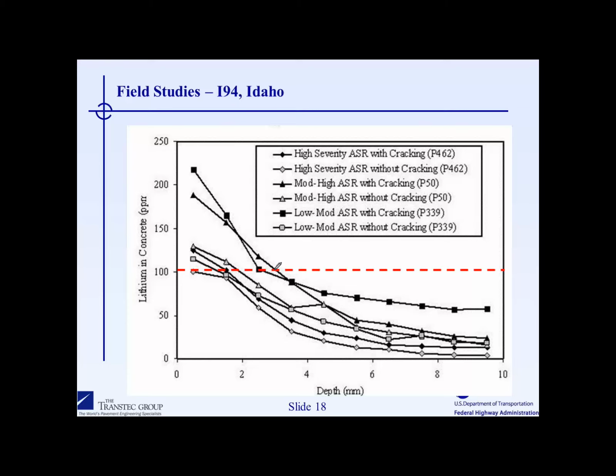So in general, less than 1/8 of an inch of penetration. And this was really useful information to have, because this pavement is 12 or 14 inch thick concrete pavement, and we've shown from this data that we're only getting depths of penetration into the outer 1/8 of an inch. Now typically that surface concrete in the outer 1/8 of an inch would have been the concrete that would have already carbonated over the years, and the pH would have already essentially suppressed ASR in that upper region.